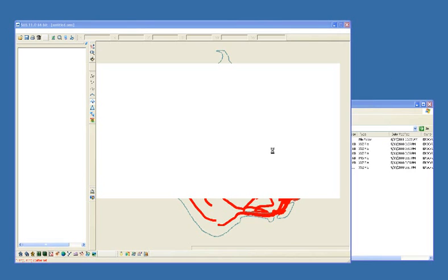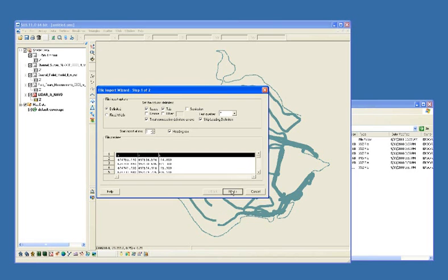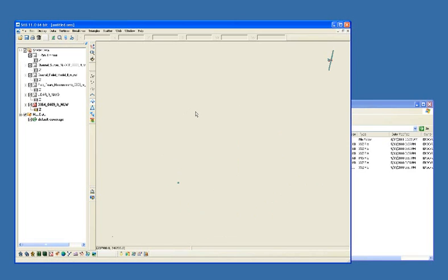All right, it's read all the points in, and now it's triangulating. So we're at the next data set. All right, and we have got all 6 of these loaded, and we see our screen here. If we zoom out to everything, which is what this second option here does, click Frame. Frame normally expands the screen to encompass all the loaded data.